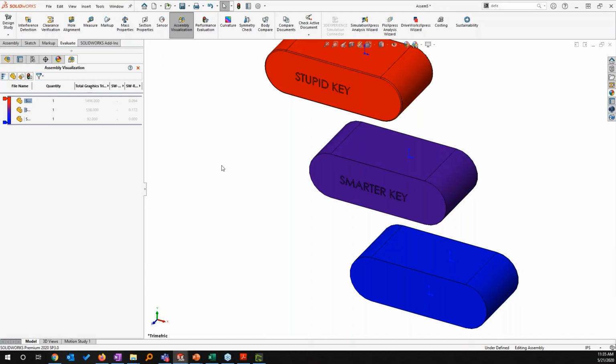So simplifying, keeping it as simple as possible, recognizing that every single small face needs to be accounted for, even if it's internal. Don't just trust the things that you download from McMaster-Carr. Make sure you have a process in place where you start to evaluate whether or not you've improved the graphic triangles of the model to make sure it's no longer as horrendous to your assembly. If you can have a configuration that uses all the same mates and the faces, but basically can be brought in and is simplified, that's really something that is important to have.